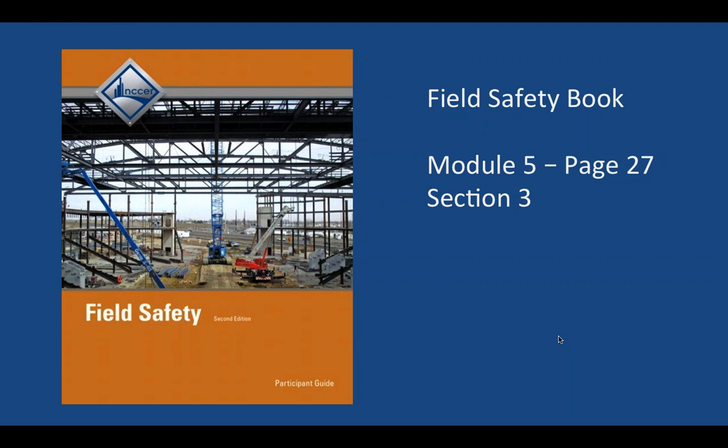And in addition to that, there are different requirements for operators to meet. Number one, they have to understand and be familiar with the associated operator's manual. So if they're on a JLG, they need access to the operator's manual for that JLG aerial lift, or if they're on a Genie, the one for the Genie. They also have to understand the procedures and warnings in the operator's manual and those posted all over the aerial lift as well.